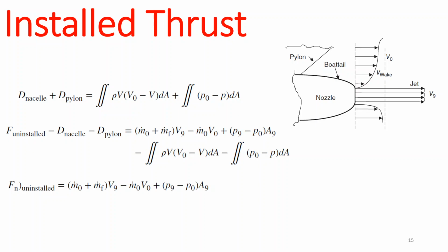of the pylon and the wing on your engine, which is going to be a momentum deficit because of the wakes, and also the drag forces that are going to be present there because of the reasons we explained, right? And then you have to do the calculations and give me the installed thrust, right? Usually you don't take the double integral in this course, and also in the real world, if you were to calculate thrust. Let's solve some examples of it, hopefully.